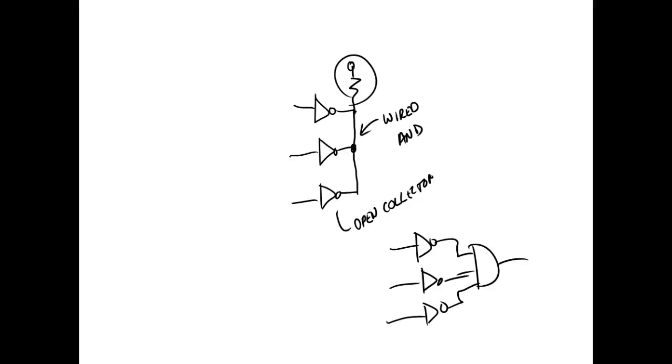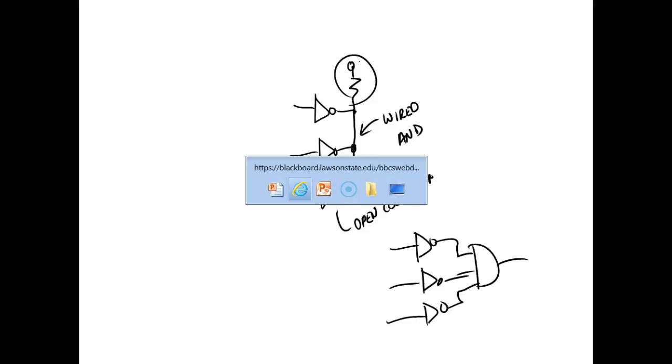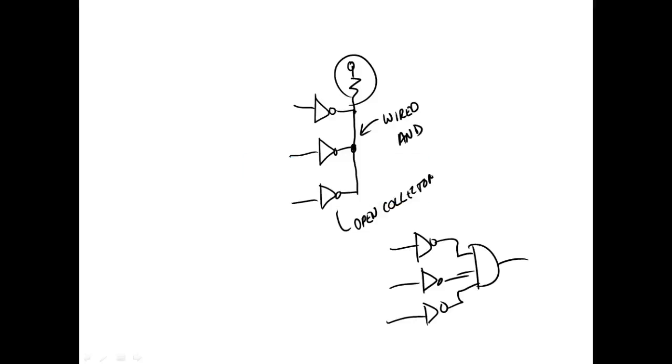So that's why, when you look at the 7400 series, there are tons of them. You understand that? Because these are all inverters. So 7404 is an inverter, 74S04 is an inverter, a 74HC04 is an inverter, a 74HCT04 is an inverter. So what we're doing here is changing the speed power characteristics. We're going to a different family of the same chip.